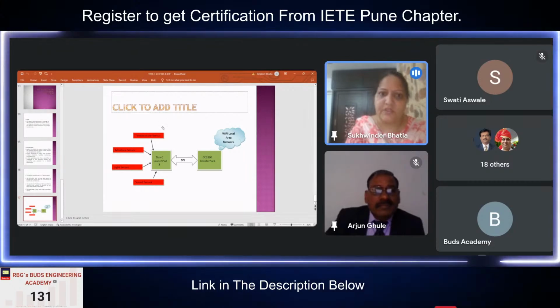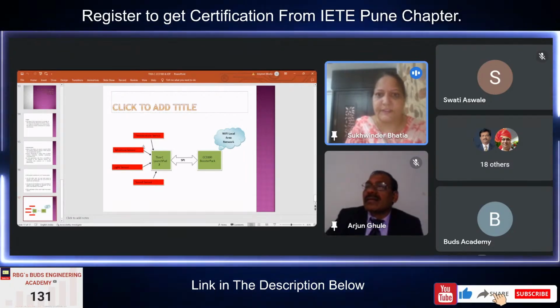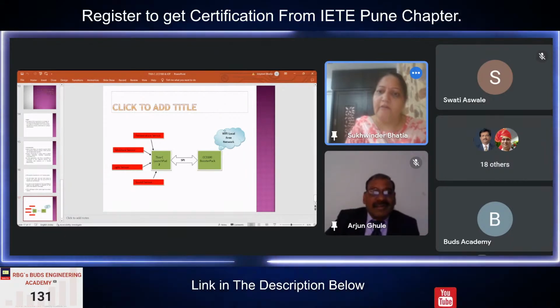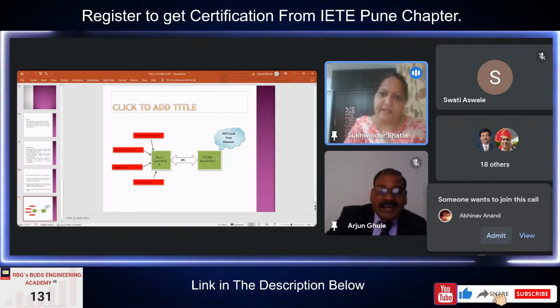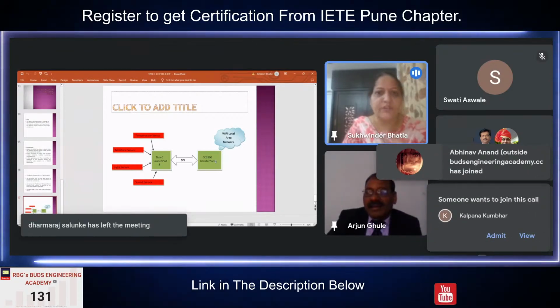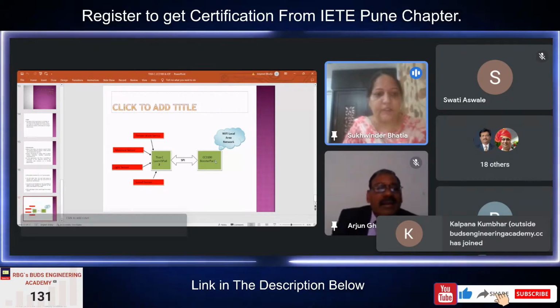Temperature sensor in my case, then my light sensor and moisture sensor. And then through CC3100, which has an IP address, this is now connected to a Wi-Fi local area network, from where, if I type this IP address in any web browser which is connected to my network, I'll be able to see the values which we have created, and see all the values.